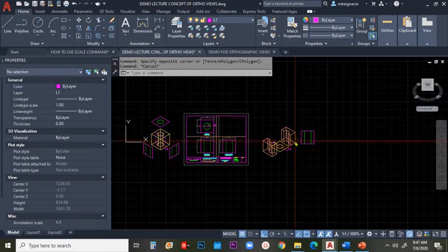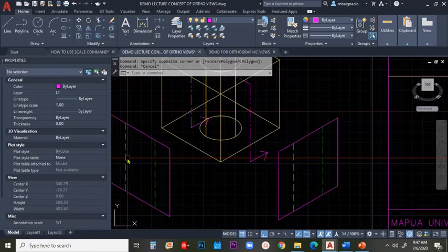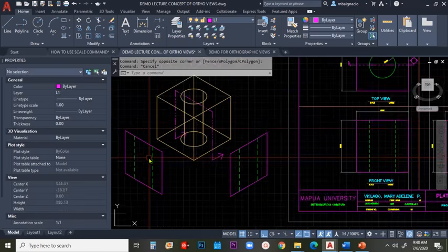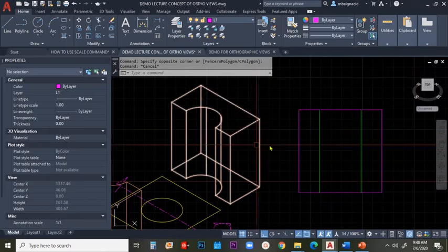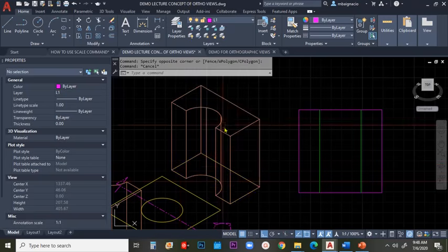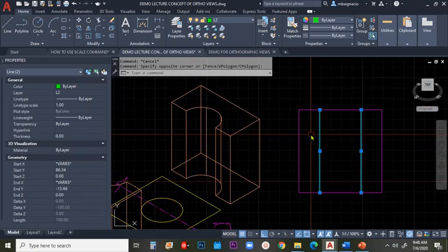As you can see, hidden lines are only used in order to represent part of an illustration which is behind a face of an object. Since we have already spliced it or cut this down into two, exposing the visible side on this area, we now use the continuous lines as a representation of the line visibility.